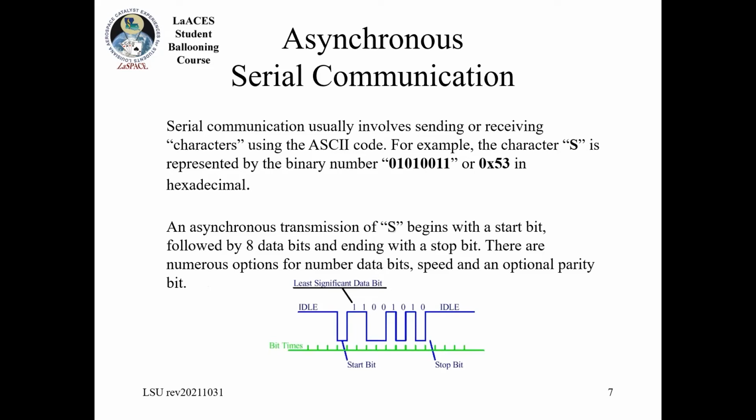So the way that this works, for example with your actual serial, i.e. the UARTs, is you have a signal like this on the bottom. You can see on the green hash marks here, that is the spacing set by your baud rate. So you've set a particular baud rate where this is the first bit, this is the second bit, etc. Each one of the devices is counting like that.